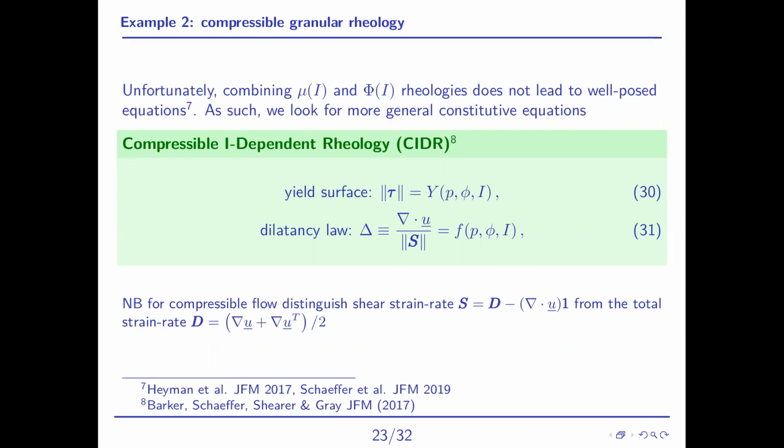Like if you've got a building, say, on a sand bed or on soil, the deformations are really slow, right? And so those kinds of dynamics are very quasi-static. But what is really key in those scenarios is the volume fraction. As you shear at those slow rates, the particles, which are potentially very stiff themselves, have to get around each other. As they get around each other, they create voids. So in order to support that shearing, it can expand. Or if it doesn't expand, it creates massive stresses and pressures that can ruin your foundations or break your grain silo or something.